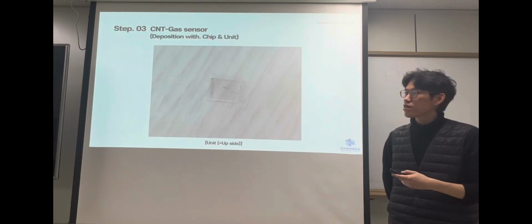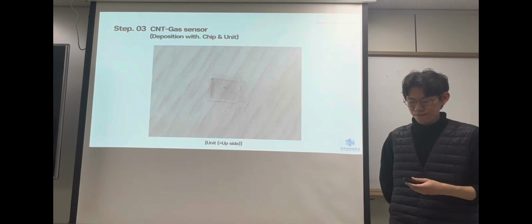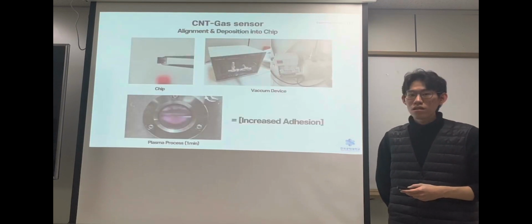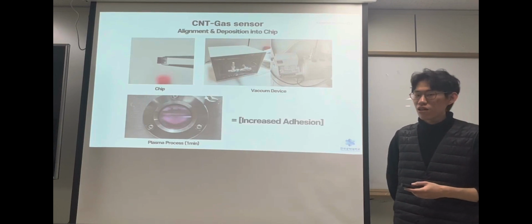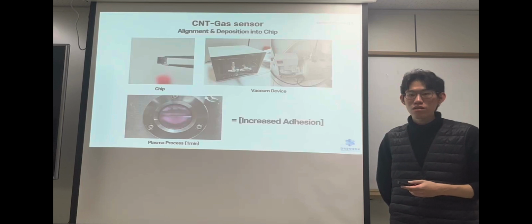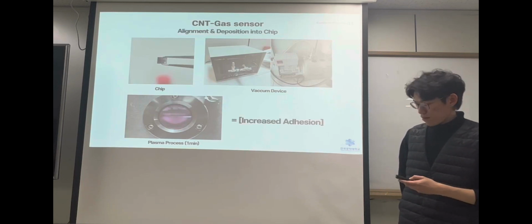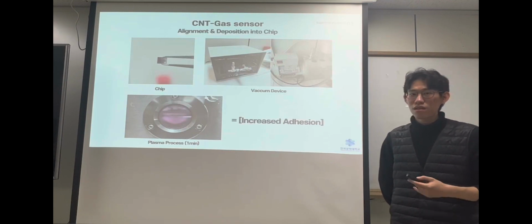This is our unit, which consists of PDMS above vertical CNT. We will attach it on our chip. To ensure good attachment, we decided to use a plasma cleaner. However, plasma may harm PDMS, so we chose to clean the chip instead. After 1 minute passed, we can find that the adhesion between the chip and unit increased successfully.